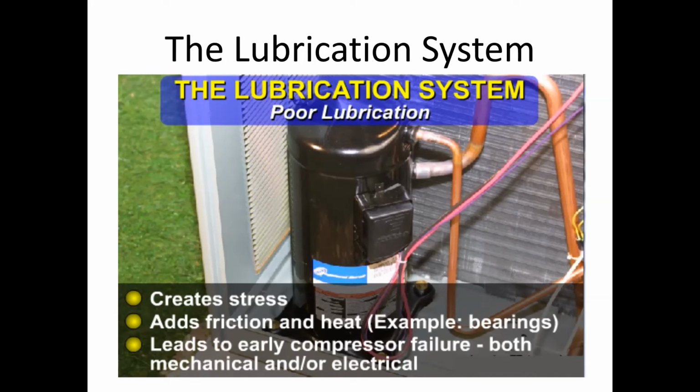So line set issues, like I mentioned earlier, if you've got a suction line that's oversized, or a lot of oil traps, either intentionally or unintentionally, in your refrigerant lines, that can cause the system to not pull the oil back to the compressor. Not having oil washing over those internal moving parts can add friction and heat.